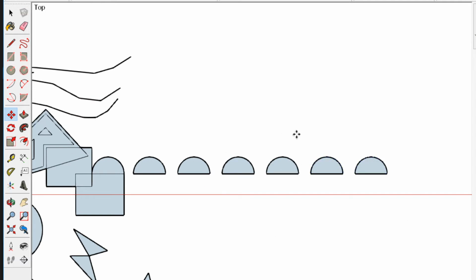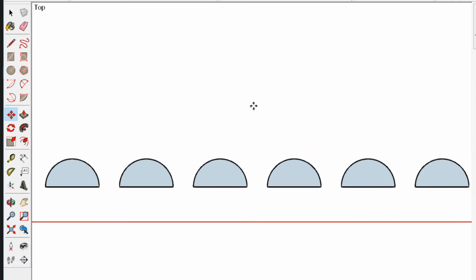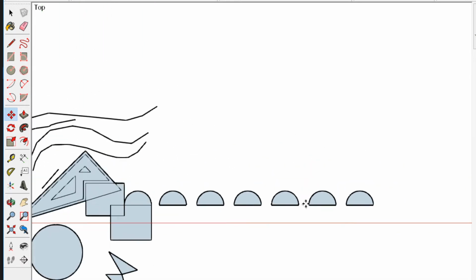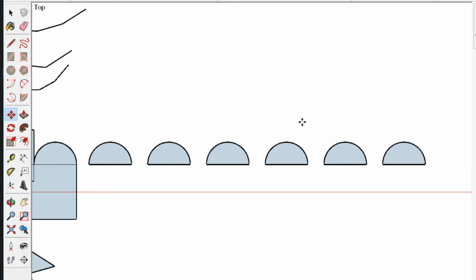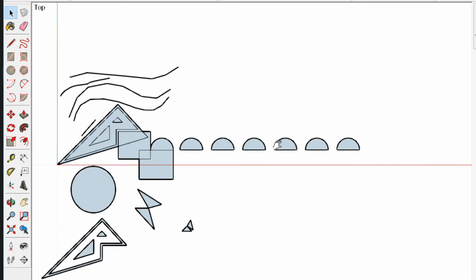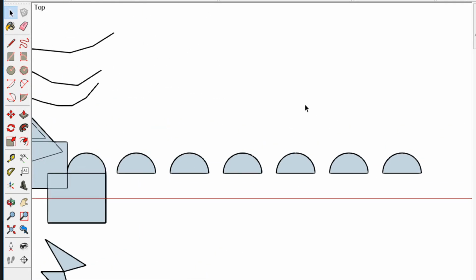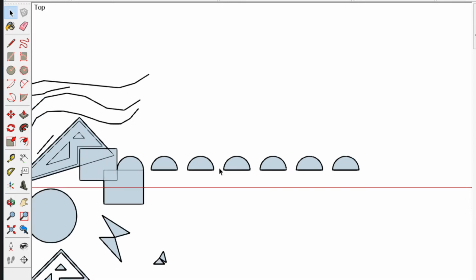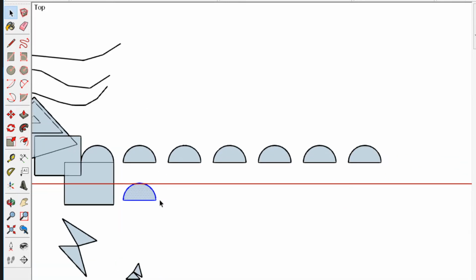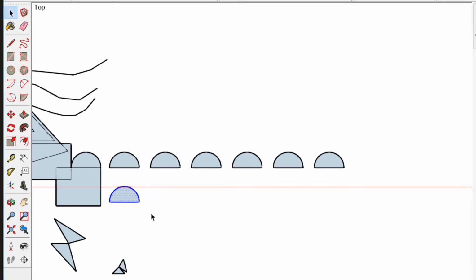Since I haven't clicked anywhere else, I'm only using my camera movement, I can still edit the number of copies. 3x, 2x, 5x. But if I click anything else like spacebar or cancel the command, and I try to hit 5x, nothing's gonna happen. Another way to do this is to use divide instead of x, which is times.